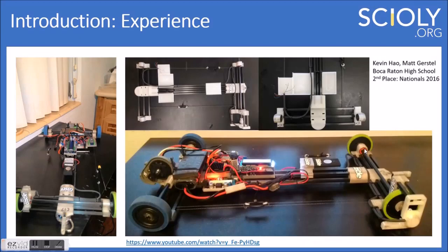You can see our axle was carbon fiber. It's this carbon fiber rod that was fitted into these ball bearings here. We used Bainbot wheels for all 4 wheels. You can see this laser pointer in the center here that was used for aiming, which played a huge role in our success. The rotary encoder at the side here keeps track of axle rotations, and that's how we figured out the distance we were at and controlled that with the device.